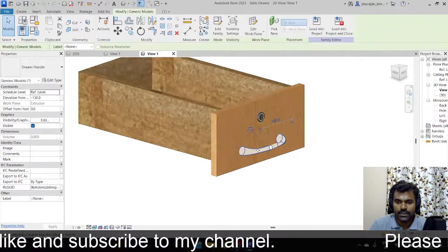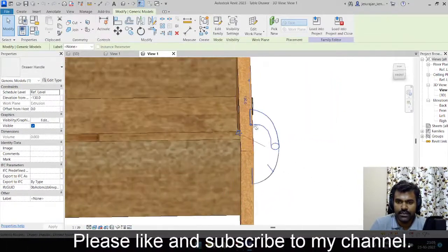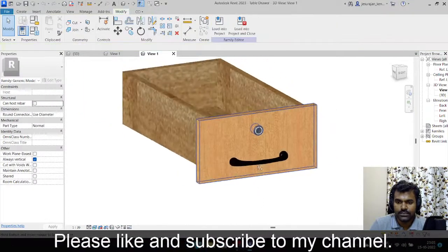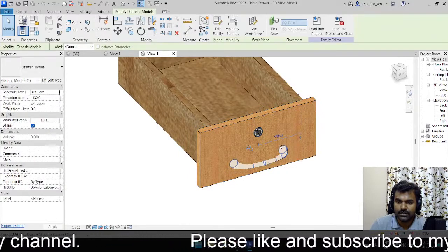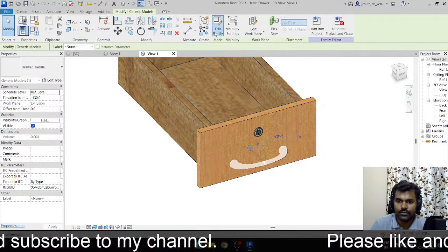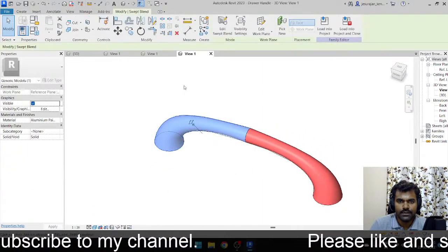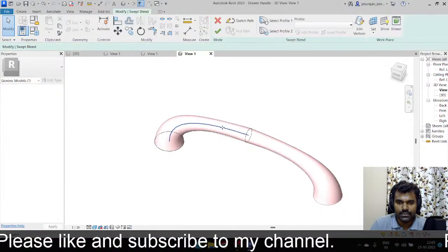Okay, and I have a handle family. Even for this handle family, I have not modeled the screw. So for now I have modeled it from an architecture perspective, we can say. I'm just modeling to see how it looks. If I go to edit family, this is how it looks. It's just a swept blend, I believe. Yeah, it's a swept blend. If I go to edit swept blend, you can see the path here.